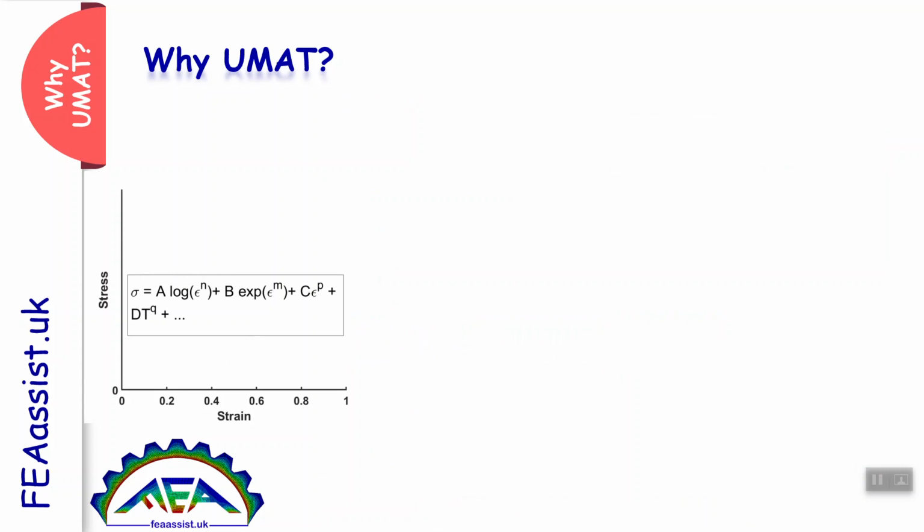So what can you do? You need a place to write this equation, or your equations, and tell Abaqus to obey this behavior to solve your problem. This is the reason we need UMAT, because our equation is new.